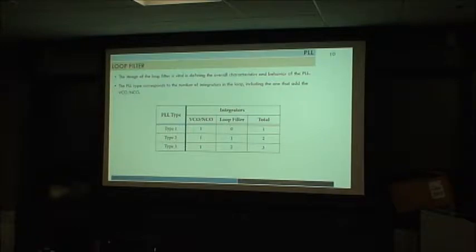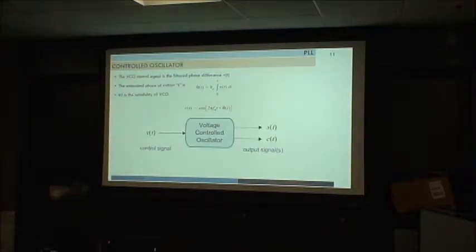Depending on how your frequency is changing, how fast, or if this is just a step or a ramp or another kind of change, that determines the PLL that you have to use. But what I'm saying is that usually you will see that nobody uses type 1, because they cannot follow too many changes basically. But we will see this a little later.